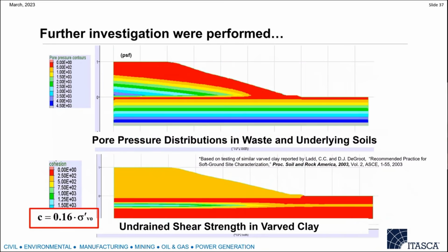So we should calculate the real pore pressure distribution. Since they have a sand layer, the pore pressure here is much smaller than the static distribution. So that means the effective stress around that low pore pressure area should be larger.